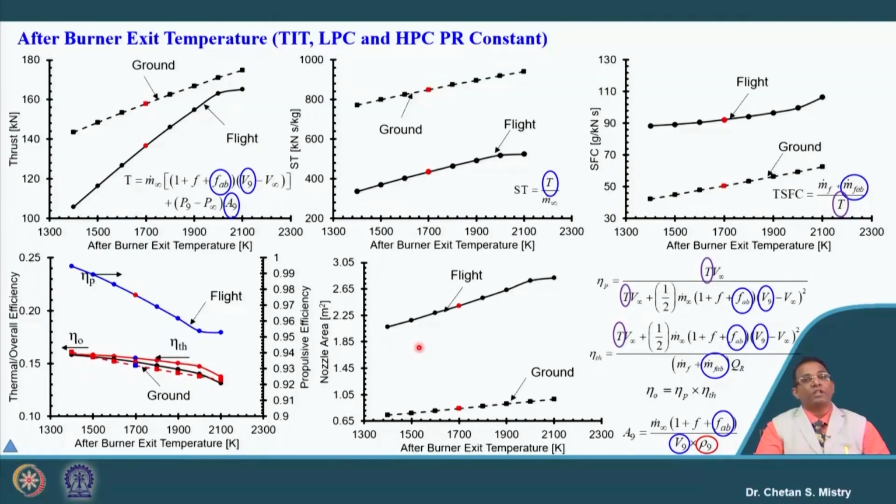In combination with the change of overall pressure ratio, the scenario will be different. This is all we can realize if we put our plot on a TS diagram. So, that is the reason why it is preferred that you use pen and paper and try to plot the TS diagram. If possible, then you do your calculation for the scenario.